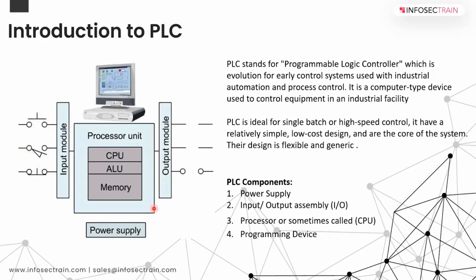While the outputs are devices that the PLC will send changes out to the system. It could be a digital input or a digital output, either a potential free contact or a 24 volt DC voltage, depending upon what we want to operate and so on.